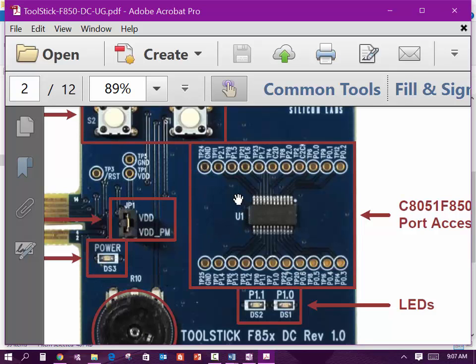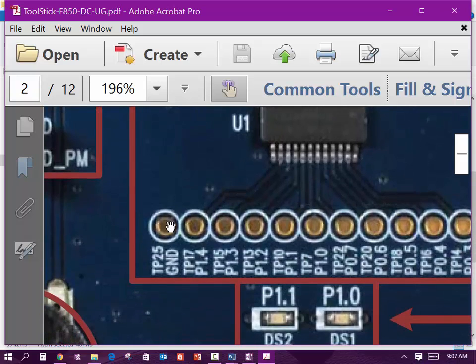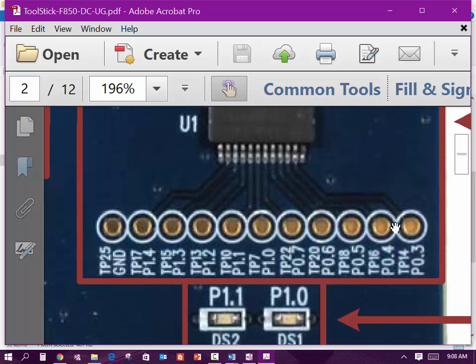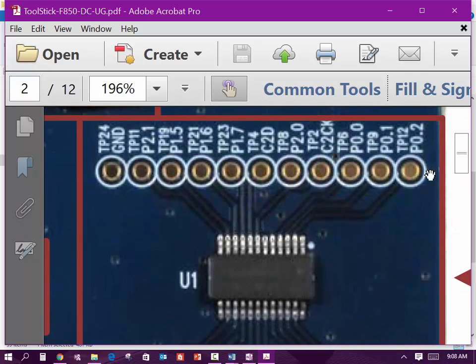And then remember, you're going to have to pull off from these pins down here. Here's port 0.7, port 0.3, and port 0 starts here, and you'll have to come off using the jumper cables to drive the LEDs. So, and you're probably going to be,